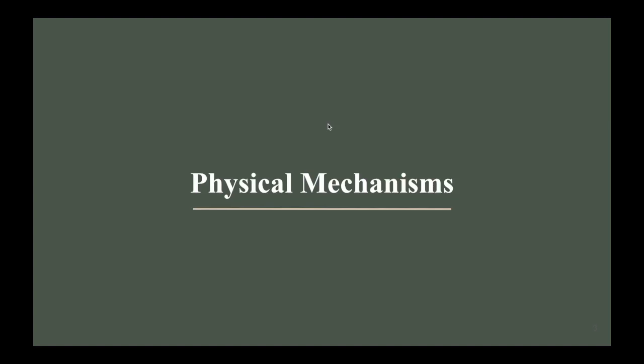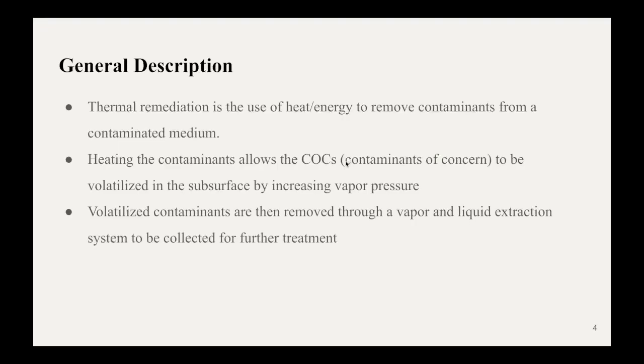So first, we'll just start with a general high-level description of what thermal remediation is. Thermal remediation is the application of heat or energy to remove contaminants from a contaminated medium. Applying heat to the contaminants will allow the COCs, or contaminants of concern, to be volatilized or evaporated in the subsurface by increasing vapor pressure.